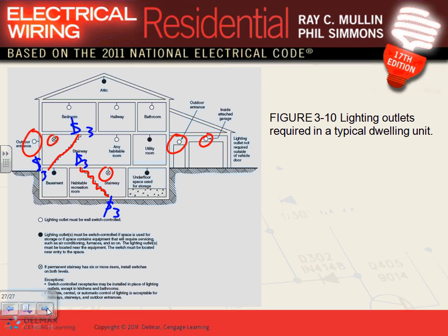Only if you have 6 steps or more. Yes, sir, code. Good design. If you have 5 steps, personally I think it's a good idea to have a 3-way switch, especially if it's my house. If it's your house and I'm wiring it to code, I wouldn't put one, because when you bid the job, you bid it based on code. A 3-way switch means more expensive and more wires.